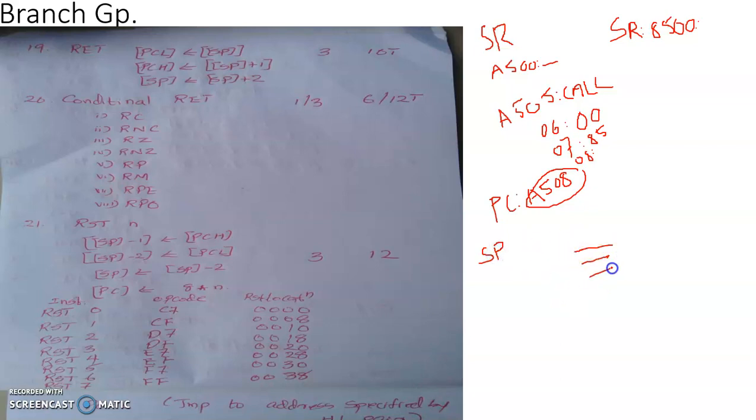So you have the stack array here. Let the maximum filled location in the stack have an address 2998. So the stack top will be 2998, which happens to be the content of the special purpose 16-bit stack pointer register.